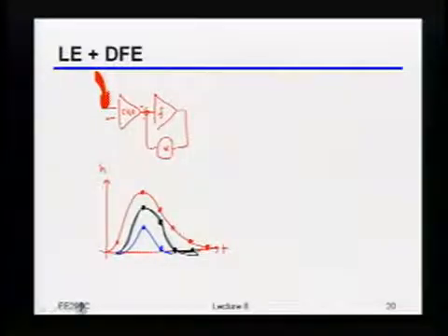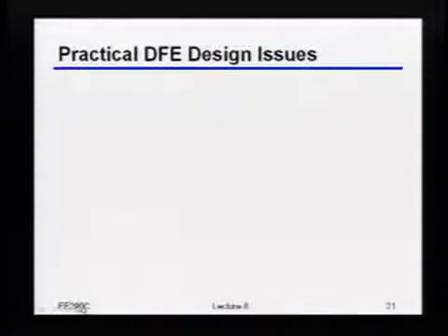Okay, so unless there are more questions on this, the next thing I wanted to briefly mention is, we talked a bit, in the context of the receive FIR filters, about how sometimes you end up wanting to interleave those things. Turns out if you're operating at pretty high bit rates, sometimes you end up wanting to interleave the comparators as well, because it gives you more time either to make the decision, or to resettle the comparator after making the decision, meaning to precharge back to the nominal state.